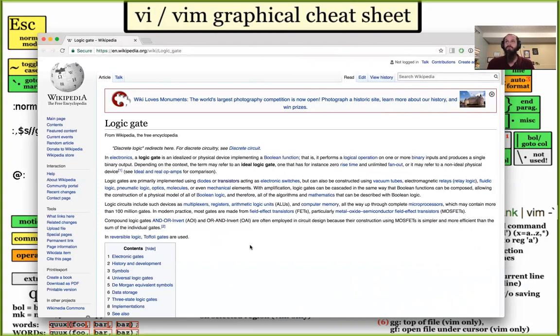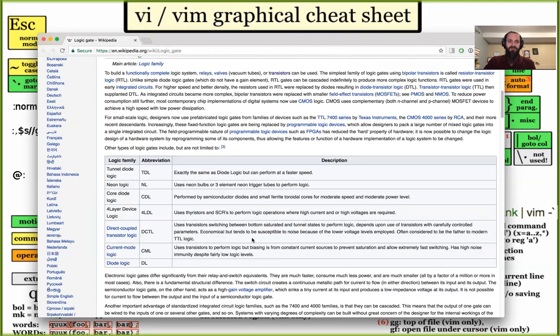Everything inside of your computer is either a capacitor, which is essentially a tiny battery, or a wire, or a clock signal generator, which we build from tiny, tiny little circuits that oscillate and generate a signal, and from transistors. And the CPU inside of your system has many billions of transistors in it that we will get to in more detail. And each of those transistors is a subcomponent of a logic gate.